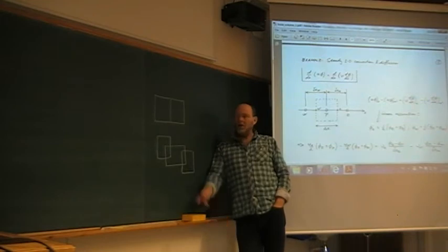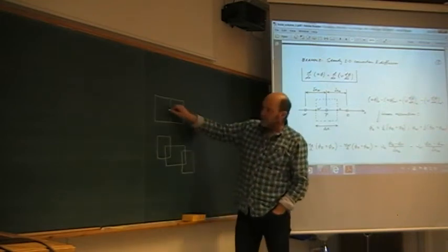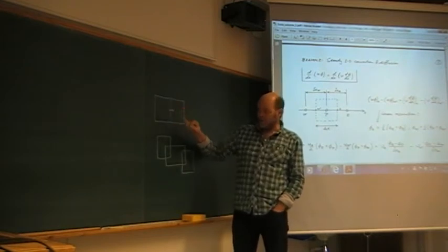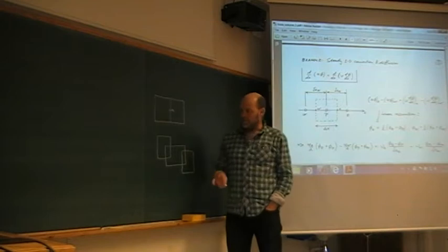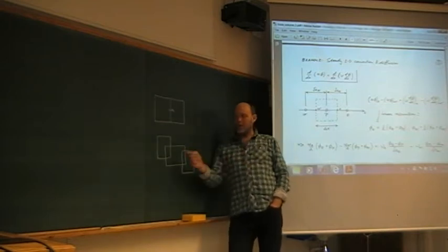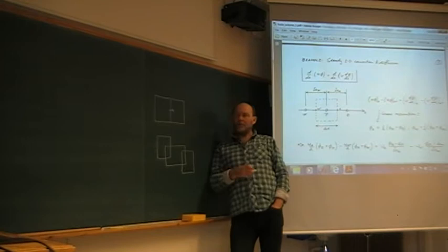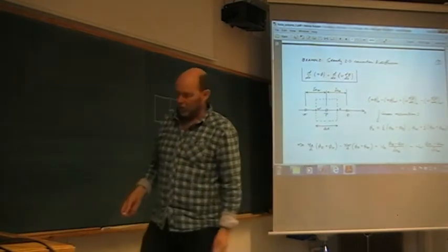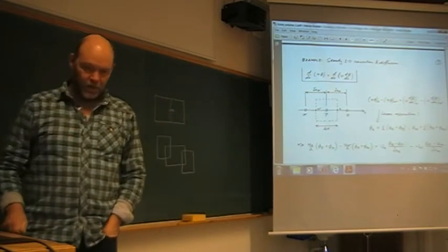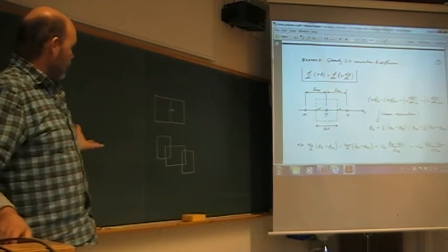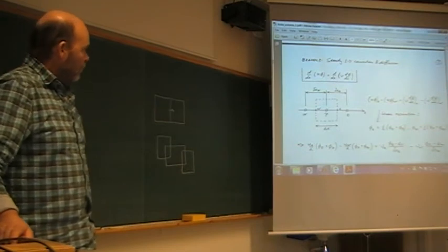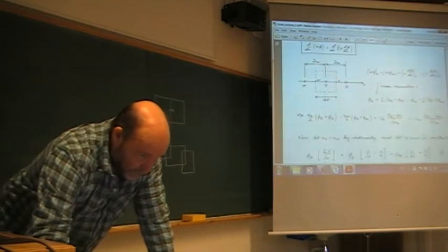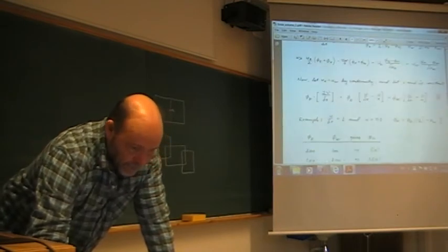That's allowed. Of course, this is much easier because you know the flux out of one cell automatically goes into the next. Not so here necessarily. So here, of course, you will have a lot of interpolation, but it's still allowed. So don't limit yourself that they have to be side by side. No, they don't have to. The equation still applies. It's an integral over any control volume. So you can do actually whatever you want. Of course, we think simple and make them rectangular and nice and put them side by side.